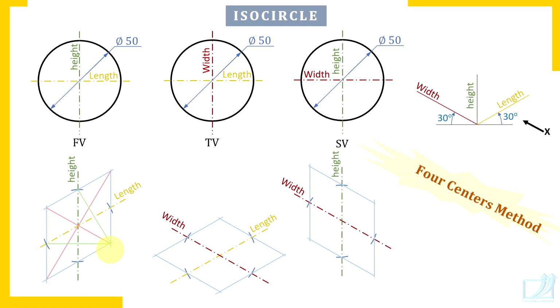Check this procedure once again. Draw the longer diagonal and shorter diagonal. And from any one of the two ends of the shorter diagonal, draw lines. Join an end of the shorter diagonal with the midpoint of opposite edges. So this way. Once again listen. Draw the longer diagonal, shorter diagonal and join one end of the shorter diagonal, check here, with the midpoint of the opposite edge.